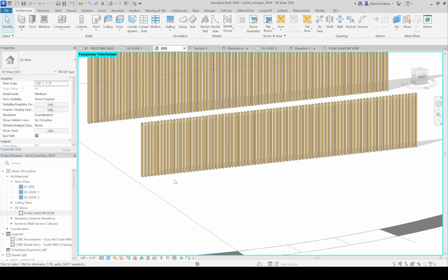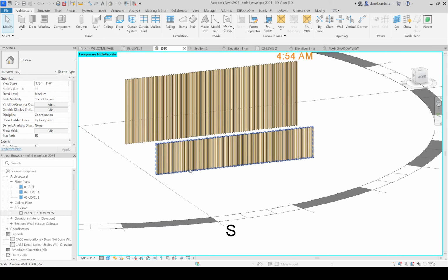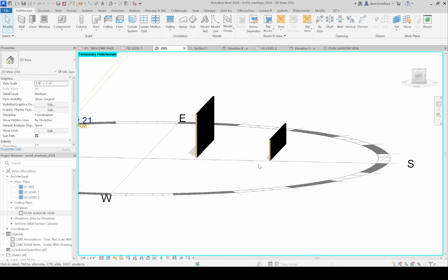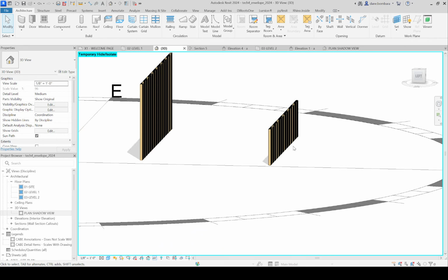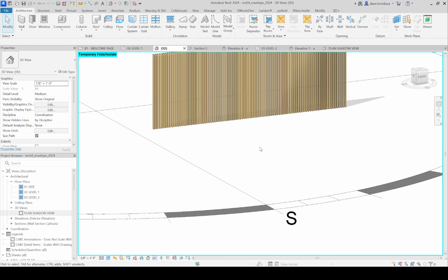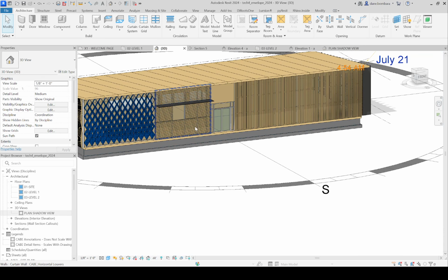Before I drew that, it would have been just a blank facade. It took me 10 seconds, and now I have vertical louvers, right? And where do we use vertical louvers? On what facades? East and west, right? So on your east and west facades, this might be a technique you use to block light, or at least control light a little better. So that's a vertical system, easy peasy, took 10 seconds.